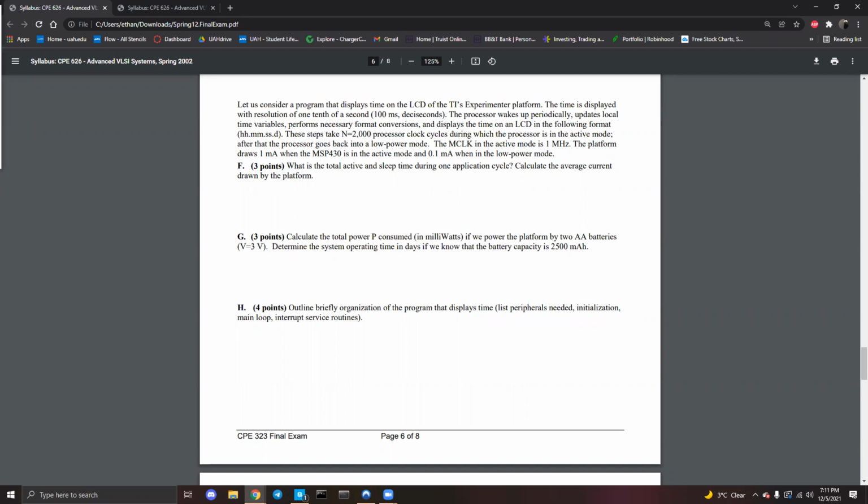If it is on the exam, it's actually not that tricky because you only need a couple of pieces of information. You need the source clock, which we know is 1 megahertz. You need the application cycle, which was given as 100 milliseconds. We need to know how long it's in either cycle, because since we're given the application cycle, we only need the time for one other cycle.